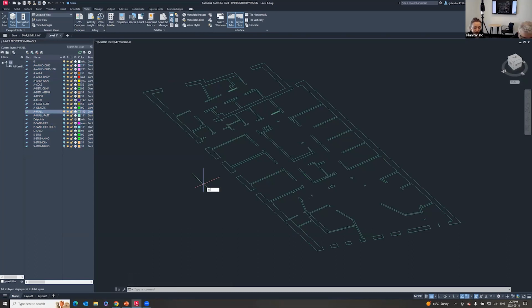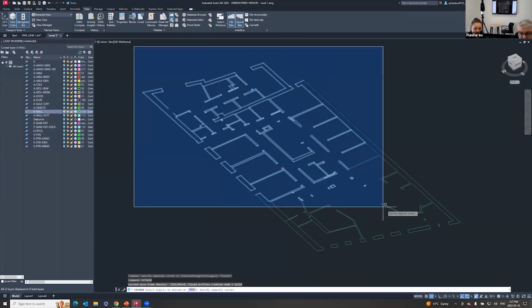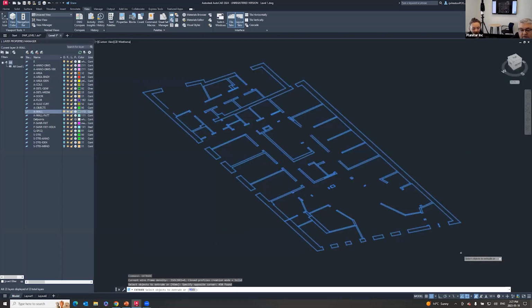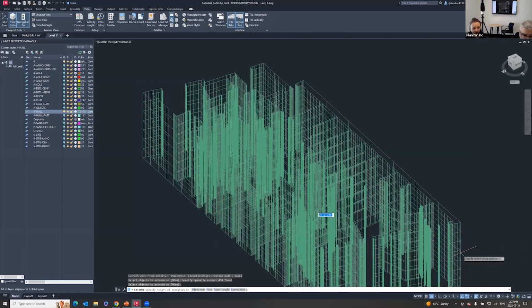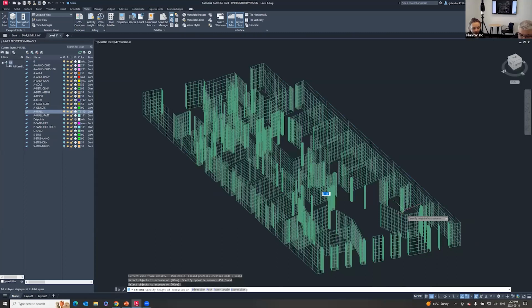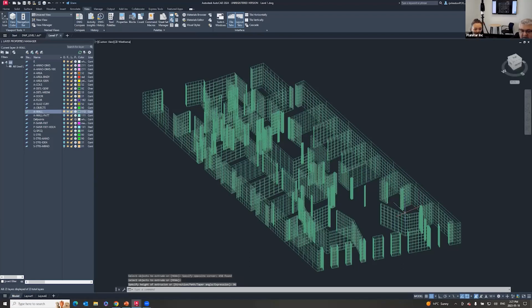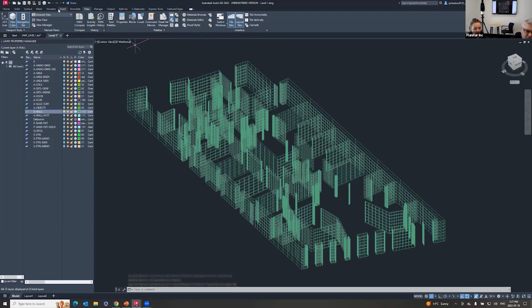You can do additional things. I'm going to do a little CAD command here that just says I'll extrude things. If I say I'll just extrude all my walls and hit enter, and say I'll just do it at 96 as an example, now I have an 8-foot 3D, and now it's just visualization.